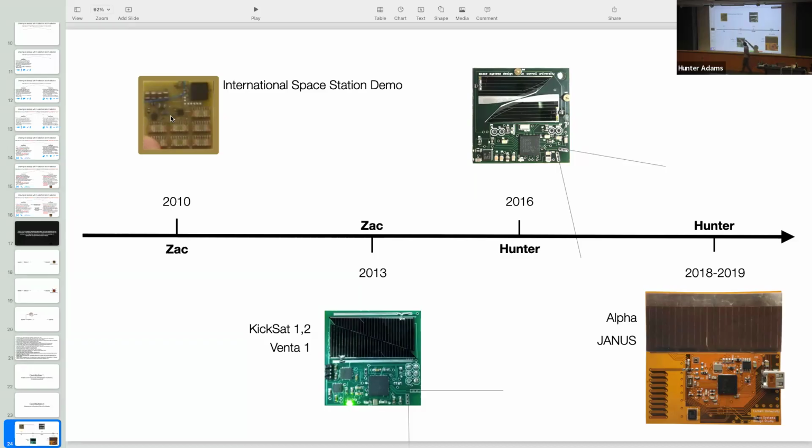But he made these little printed circuit boards that essentially just had a radio beacon on them. They were taken up to the International Space Station and put on the outside of the space station, exposed to space. This was a simple experiment: how well do these commercial electronic components do in the stresses of space, exposed to the thermal fluctuations and the radiation and everything else.